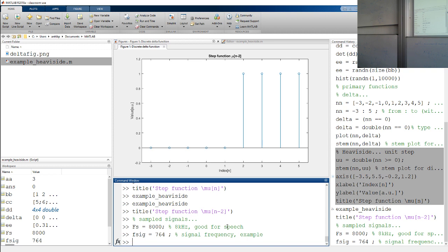We can use, for example, the higher one, so 2.4 to 3.6. So this actually has to be biased to 3 volts plus minus 0.6 volts.